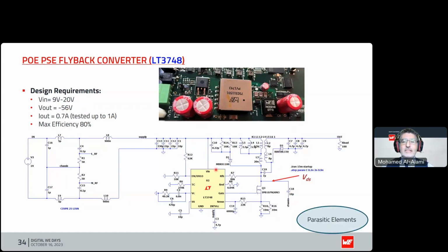And one of the things that we've also done, and we always like to do as Würth, because you know us for our EMI capability as well as power, hopefully, we've also simulated and tested this from an EMI point of view to just see the amount of noise that we are getting and the extra filtering that might be required for this. I've done this, by the way, by simulation of the parasitic components: interwinding capacitance, leakage inductance, capacitance of the drain source down to chassis, down to ground.